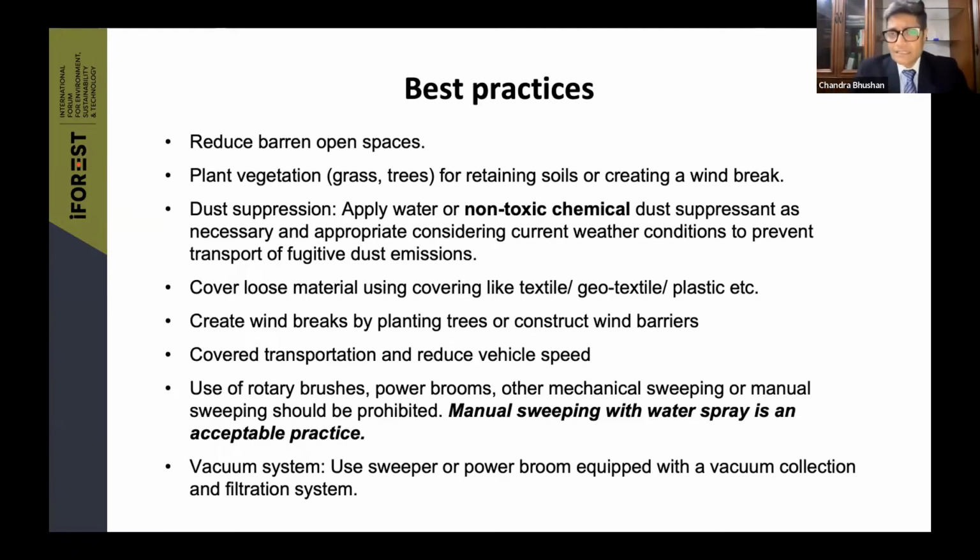As far as road sweeping is concerned, do not use any mechanical device which does not have a dust control system. So whether you are using rotary brush, power broom, mechanical sweeping, or manual sweeping, it should be prohibited if you are not using any pollution control technology. Manual sweeping with water spray is an acceptable practice. If you are doing manual sweeping, like it used to be done in olden days, you spray water and then do sweeping. Otherwise, any manual sweeping is going to mobilize dust into the environment.